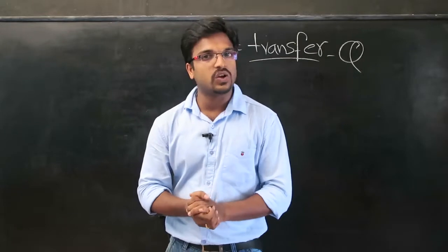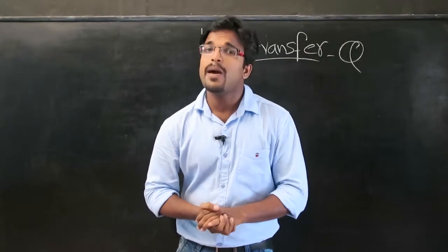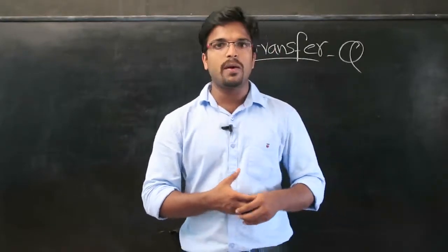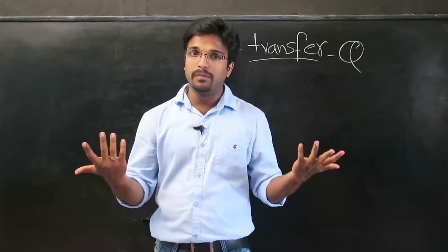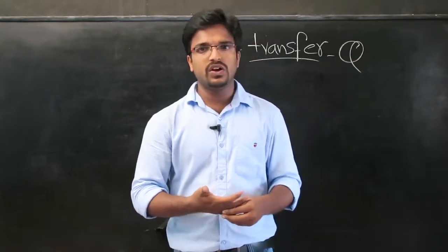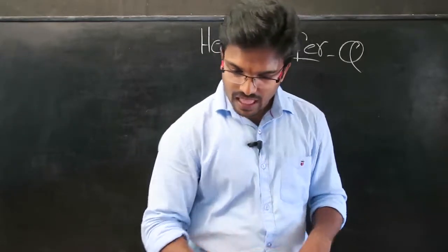So heat transfer is not a property. It cannot be stored inside a system. It's not a property. Similar to work transfer, it is also a boundary phenomenon. If it is not crossing the boundary, it doesn't have any meaning. So heat transfer is not a property, it is a boundary phenomenon, right?